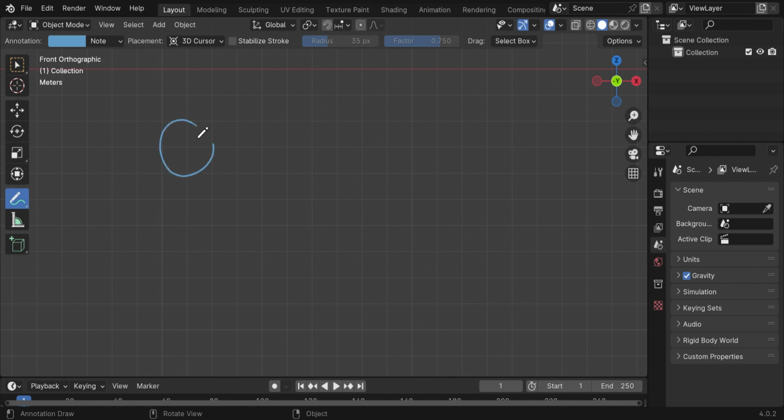I'm going to again draw the circuit, and my source voltage will be 5 volts, and in this case I'll have one resistor and another resistor going to the ground, and this resistor will be 2 ohms, and this resistor will have an unknown resistance and an unknown voltage. This resistor, say we measure across it from here to here with a multimeter, and we see 3 volts.